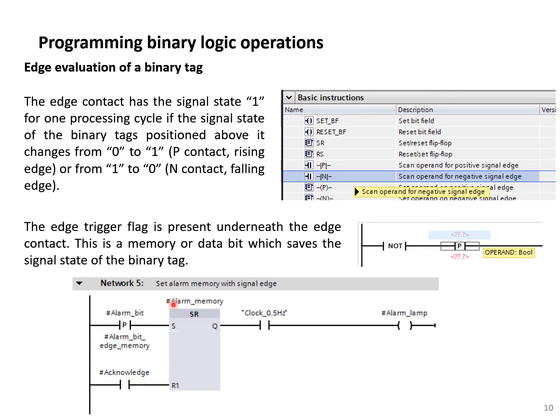Why is it good? Because, for example, we have this set reset box and we want to set it once and that's it. We basically don't need the logical signal here, either true or false, and this box will stay true and the Q output will stay true. Okay, once, for example, we acknowledge it with another push button, then we could reset it.